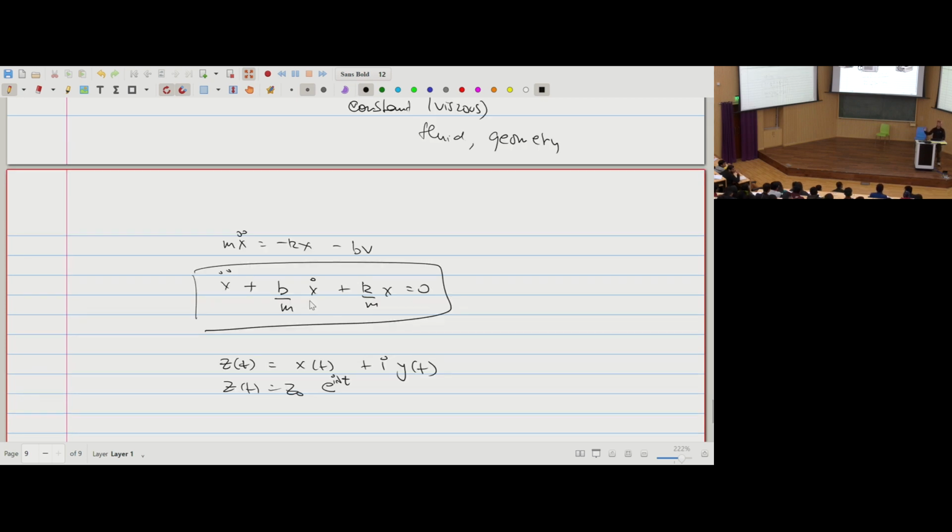Because you get different situations in the solution, depending on the sign of the discriminant of the characteristic equation, you will get either an underdamped system or an overdamped system. In some situations, let's say the damping constant b is very large, an extremely highly viscous fluid, then the solution you get is non-oscillatory. You pull it and leave it, it just goes to 0, or asymptotes to 0. x is a function of time. That's what I'm talking about.